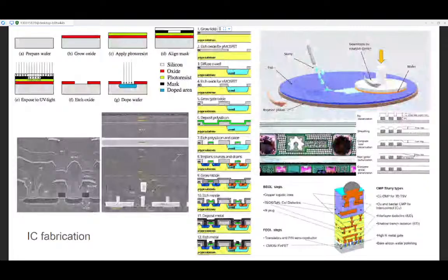There's a huge problem with that. This is what a chip like that looks like. Every step that I add, metal 2 becomes really, really weird. So that means that that's my limit. If I add one layer of metal, it's all uneven. Then I add a second layer, it's really, really uneven. There's no way I can have a third layer of metal. That was the state of the art for a long, long time, until they came up with the idea of polishing the wafer between each metal layer. So you start here with a very uneven surface with metal layers, and then you polish it.